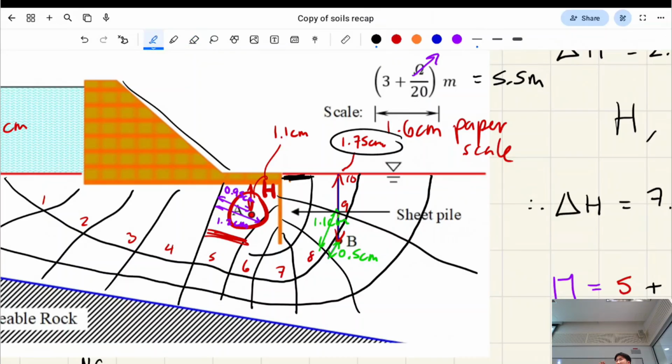It's where the soil is touching the water and the water is flowing up from. Do you know what I mean? That's where you're going to experience quicksand. And these other squares are going to be less critical than the innermost square. So this is the point at which you'd first see quicksand effects happening, which is what we want to design around.